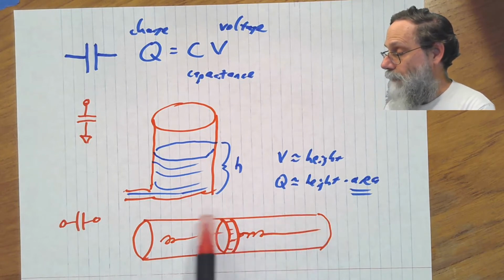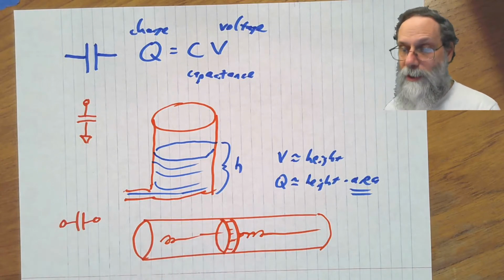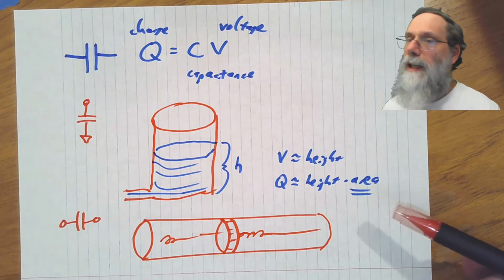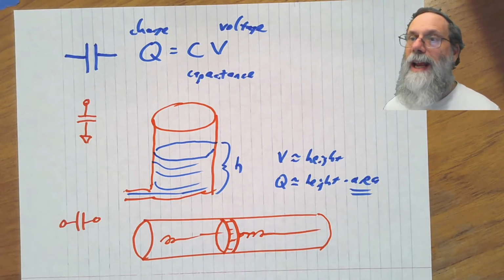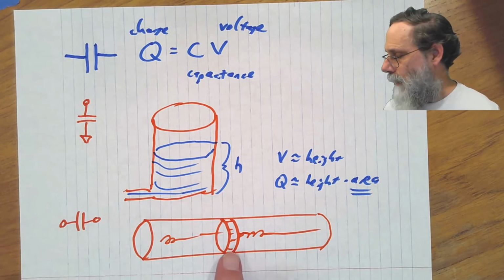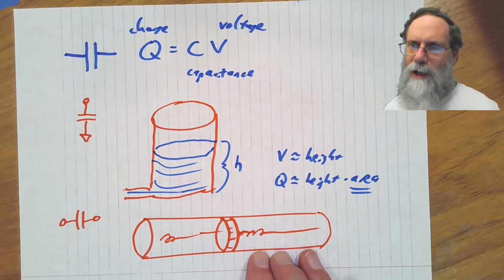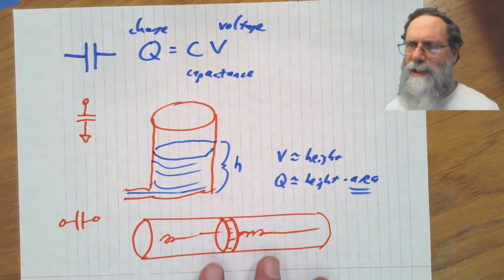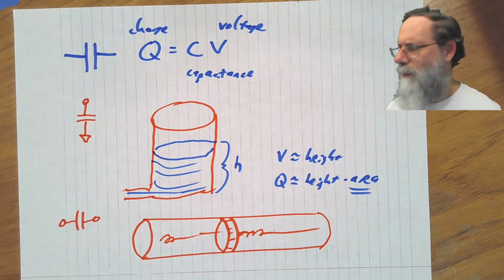And the charge is going to correspond to how much volume of water it took to get that effect. Again, we have a rough correspondence with capacitance corresponding roughly to the area of the piston, though the analogy isn't quite as good here because we have to take the spring constant into effect, and we're interested in pressure rather than force. So this analogy takes a little more care to work out, to get things that are numerically corresponding and not just intuitively similar.